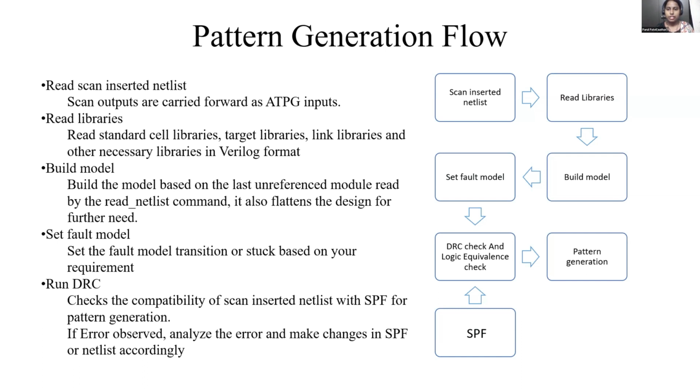In our tool, which is the Synopsys TetraMAX tool, first we give it the scan-inserted netlist, then we read the libraries. We must have some internal IPs or modules, or we have taken some modules from other device designs, so everything that is being used in the design will be read. Then a model will be built. The model is a flat model of the design; you can think of it as a schematic. The tool forms a schematic for itself to run this pattern generation.